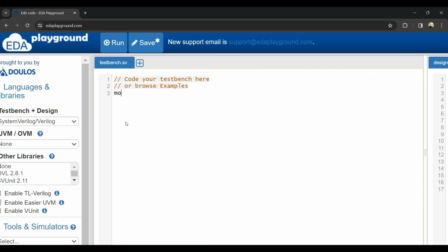Now we will write the test bench module. What are the inputs registered? Register [3:0] parallel input and register clock, and the other is load. Okay, now what is the output? S0. Now I will extract the inputs and outputs from the design code. What are the inputs? Clock, PI, load, and finally S0. Okay, now I will give the first clock signal.